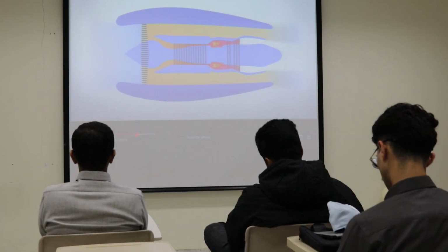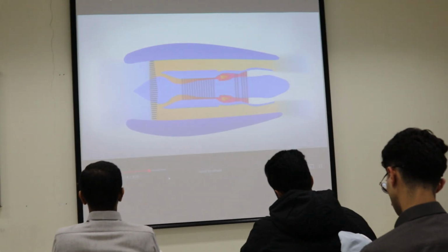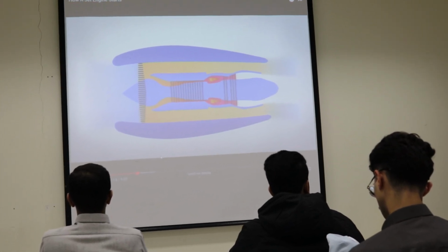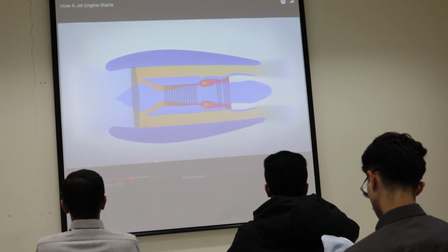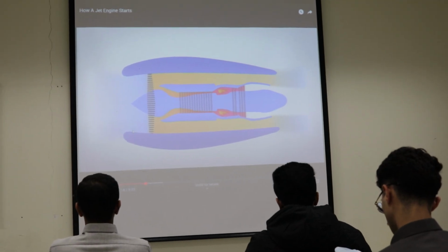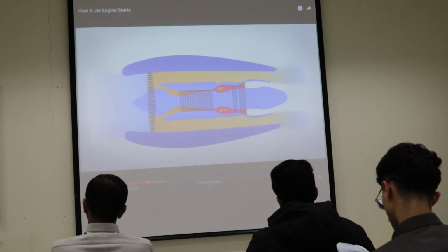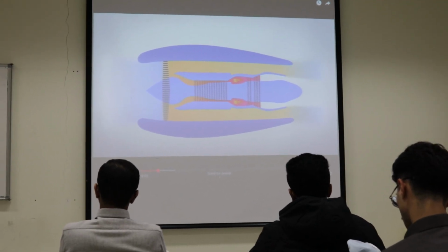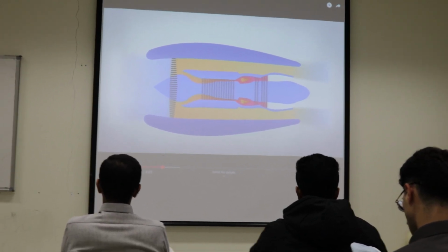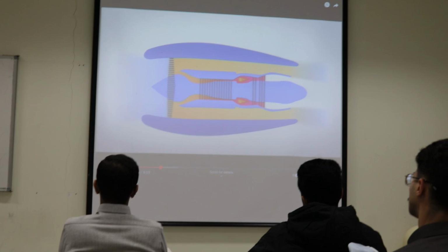of almost 12% of the full operating rotational speed of the shaft, which, for a high pressure turbine, may be spinning at 100,000 RPM as a matter of fact. Okay, from 60 maybe to 100,000 RPM. To reach this speed we can use the air fan, the air turbine. And then for the fuel to start to be injected in the combustion chamber, it has to be running at almost 25% of its rated speed. Then we have to generate this speed using the pressurized air that can run the air turbine.